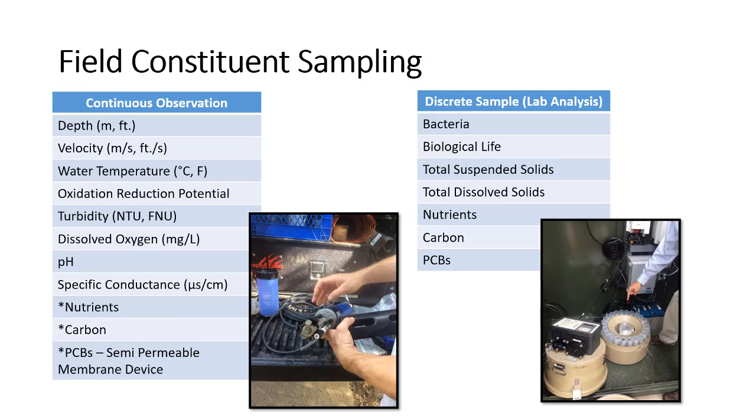So let's think about some of the important information that you're trying to get at with these measurements, right? You're looking for concentrations. You want to know what is the concentration of one of these many things in the water, and you also are interested in loads, right? The concentration is going to be a mass per volume, so a milligram per liter, and the load may just be a mass per time. So if we're looking at an annual load, we're interested in saying, over the course of a single year, how much sediment crosses this particular section of river.